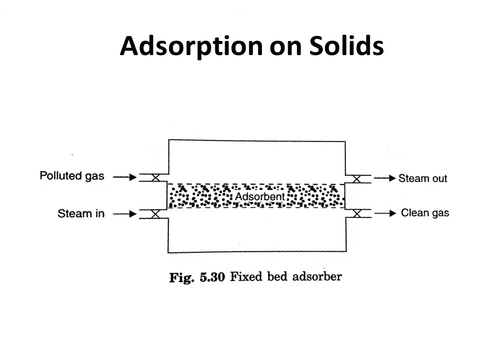But in case of chemisorption, it results from the chemical interaction between the solid and the adsorbed material. It is usually irreversible. The molecules are held to the solid surface by chemical bonds. The adsorption method is mainly used where there is a requirement of control of odor. The materials that are commonly used as adsorbents are mainly activated carbon, activated alumina, silica gel, etc.